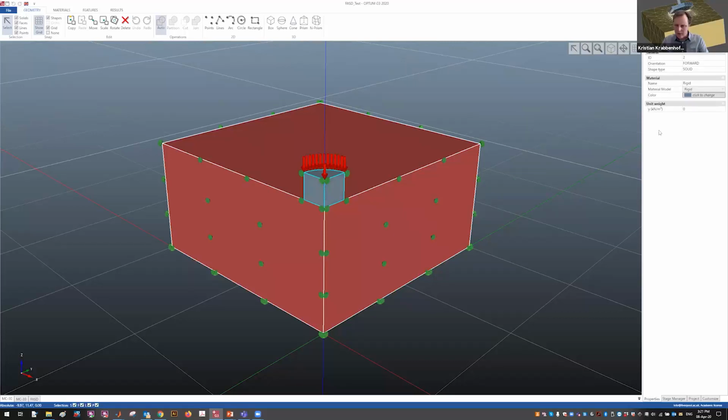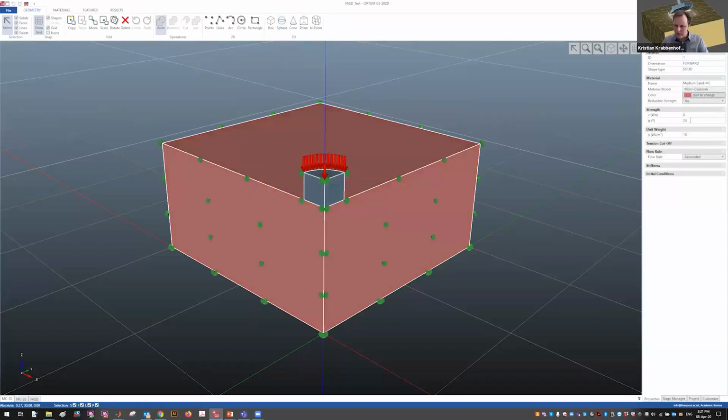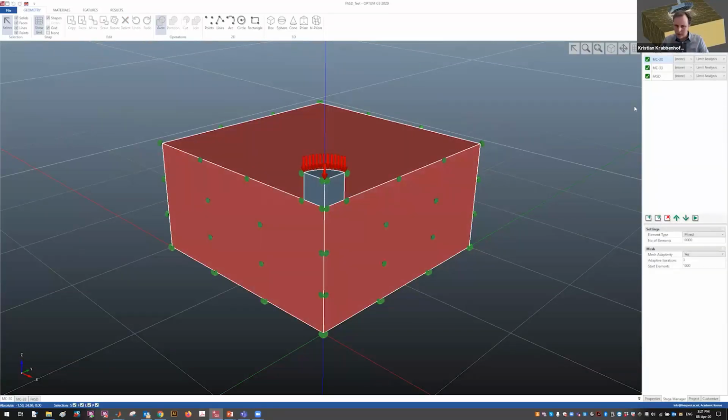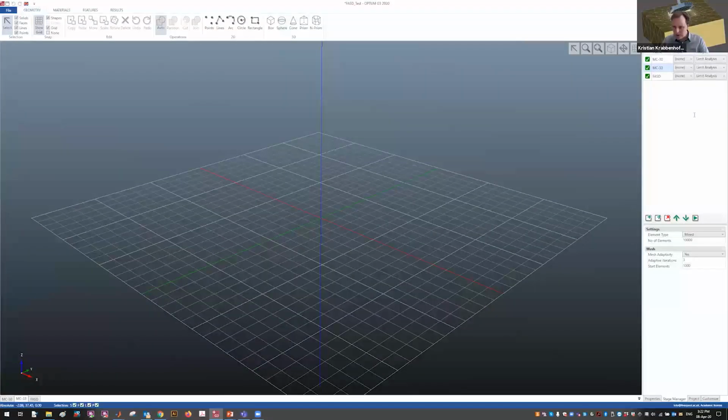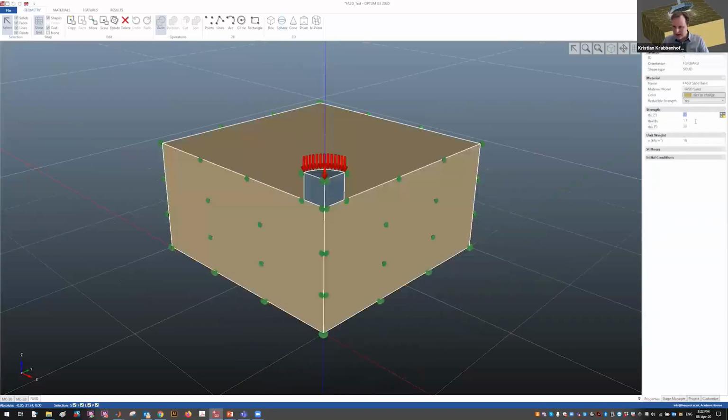I first solved the problem for a Mohr-Coulomb material with a friction angle of 30 degrees. So that's the triaxial angle, then 33 degrees, the plane angle, and then the FASD model where I have two angles. The way the input works is you input the triaxial angle and then this ratio between the plane and the triaxial angles. And then this one is calculated automatically.